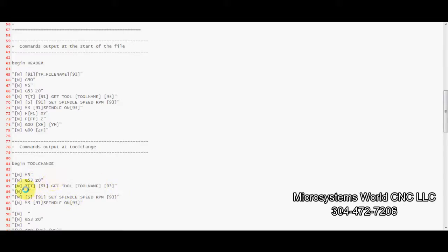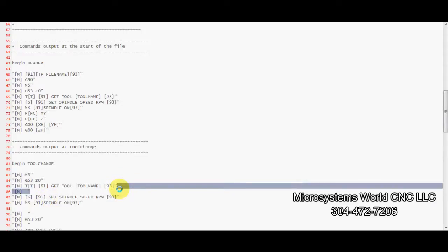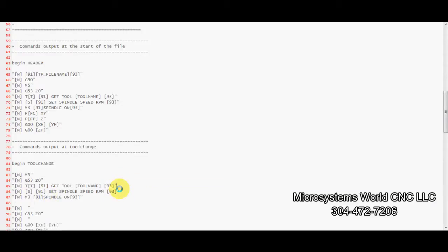Make sure that when you do any of these that you have your quotation marks on each end. That's very important. I once in a while will forget to do that, and I'll get an error when I try to run my post-processor. Also, before you start using any of these, verify that they are the correct ones to use by looking at the post-processor manual.